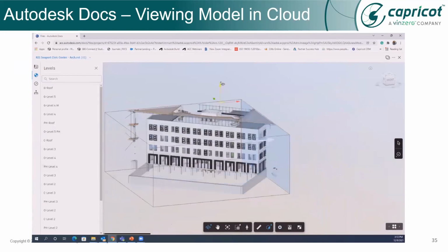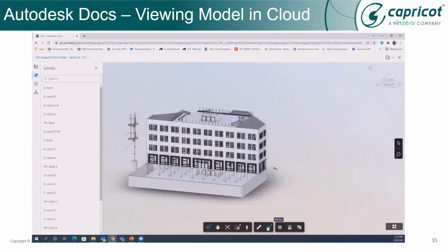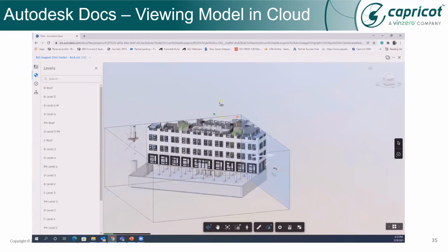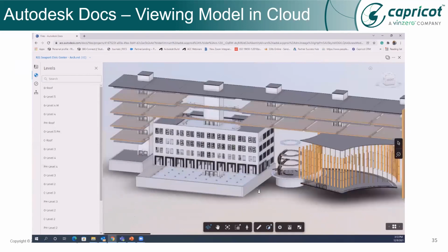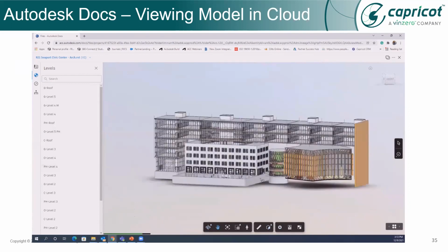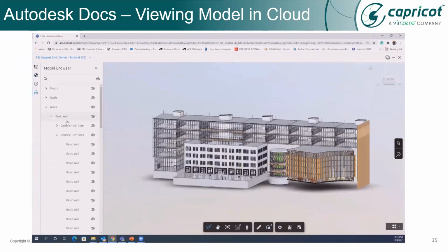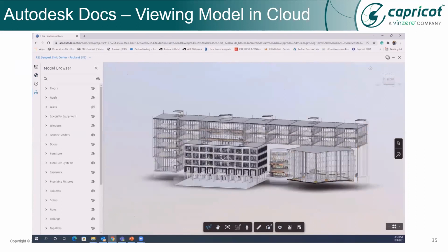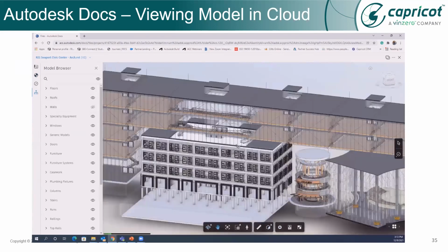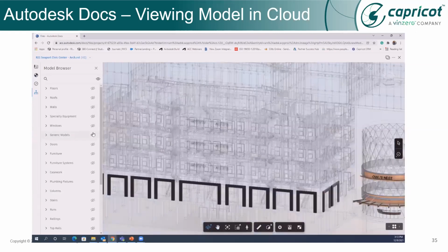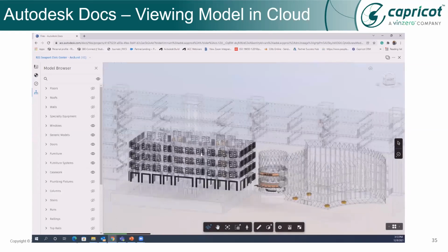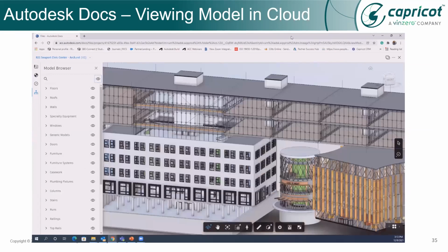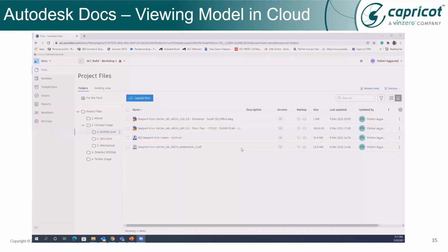There are also collaboration features in the various authoring tools like Revit or Civil 3D and even InfraWorks. These collaboration features allow you to directly upload the updated model onto the cloud. It will come to the cloud with a version update like V1 or V2, and then the other team member can compare what has been updated. There are various methods of comparing your files. Using side by side comparison or even overlay comparison, you can compare the two versions.